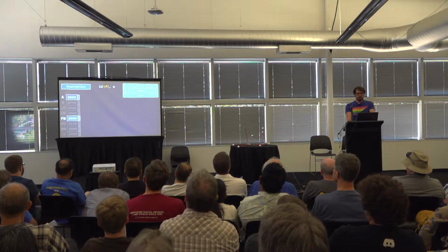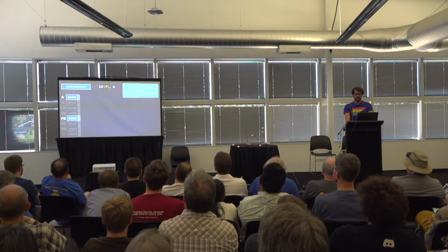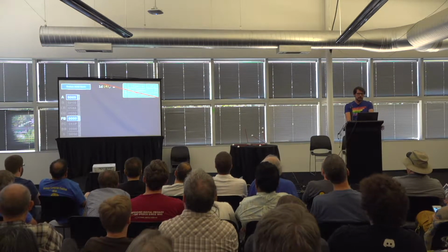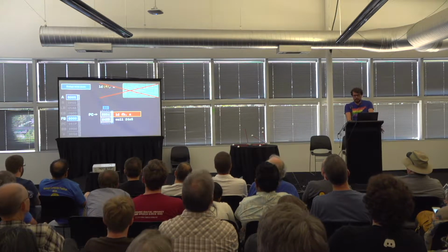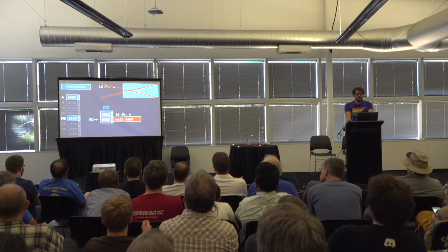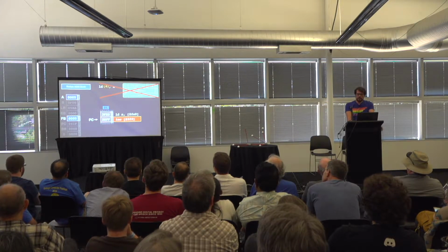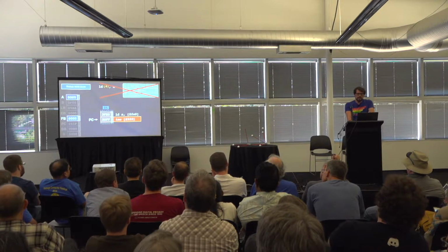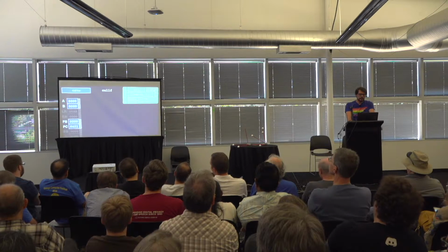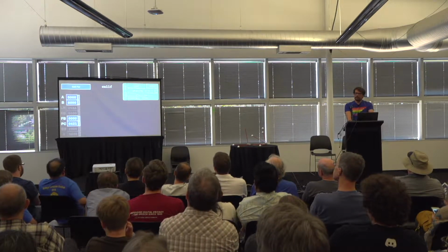The same store instruction could be used to write to the FB register in memory location 4 to switch the ROM bank, but that wouldn't work for the common case. If code in one bank wants to call code in another bank by first switching the ROM bank, load FB, and then doing the function call, writing the bank number into FB will switch out the bank the code is currently running on, so it won't be able to execute the call instruction. Instead, it will continue using some completely unrelated code that happens to be at the same address on the other bank. To call code on a different bank, the FB and PC registers have to be changed atomically.